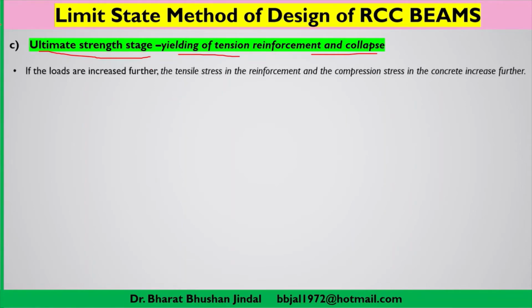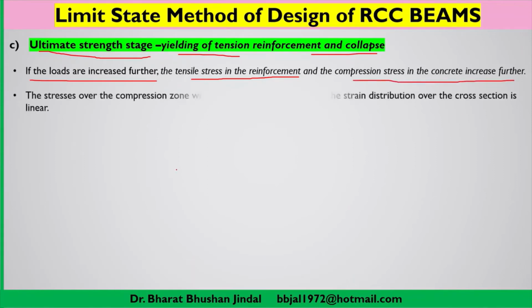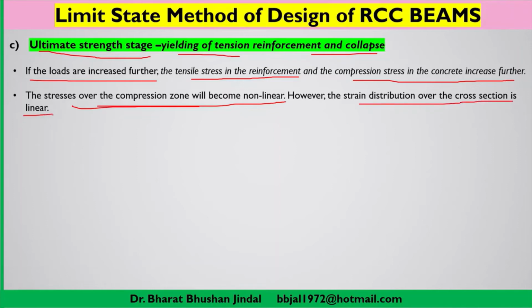Now in continuation to the previous cases where we were increasing the load, if the load is increased further, then the tensile stresses in the reinforcement and the compressive stresses in concrete will go on increasing, and the stresses over the compression zone will become non-linear. So now we are moving out of the linear phase. However, the strain distribution over the cross section is linear.